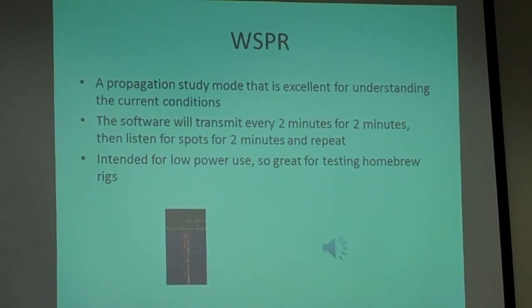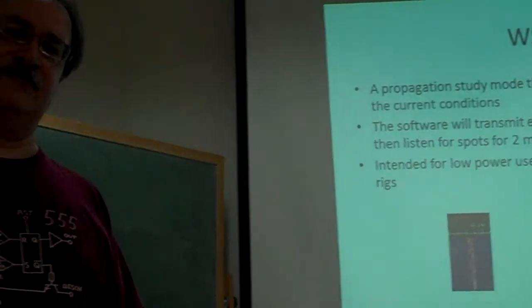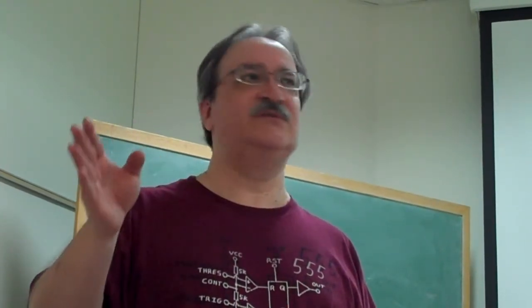The other thing that helps from a practical standpoint, if you haven't tried this yet, not to discourage you, is that the frequency allocations, the gentleman's agreements, have worked pretty well with digital modes in terms of where you're going to find people running certain modes. Yeah, there's exceptions like there always is, because it's more of a wild, wild west and more of a mix than you get between CW and sideband. People tend to honor that pretty well, so there's a little bit less of that. But most of the time, if you want to go to 14070 or 7070, 10140, those PSK 31 frequencies, they're going to be run PSK 31.